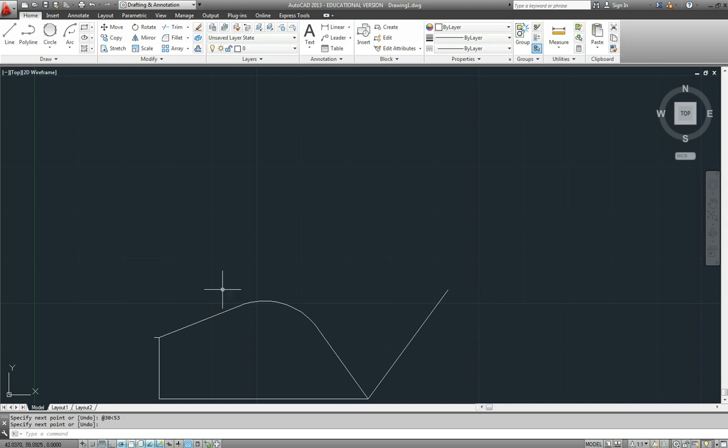And now we're going to have to come round from the other direction. So I'll start back over in Western Australia, a line from the first point, and we've got 74 degrees. Again, we've got to take that away from 180, which gives us 106. Yep. So let's go a distance of, say, 30 once again. So relative to where we are, 30 at an angle of 106.